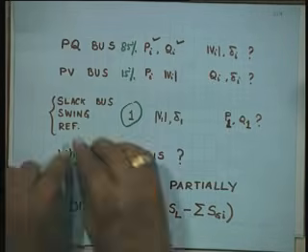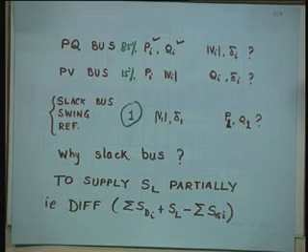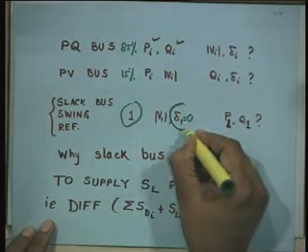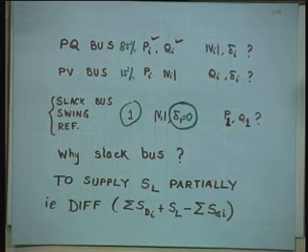First thing is, you have to refer all angles at the remaining buses with reference to some bus, and hence delta 1 is normally assumed to be 0, and the rest of the buses are referred to this bus angle. This is without loss of any generality. You can always say 5 degrees, no harm done, but why not take 0?